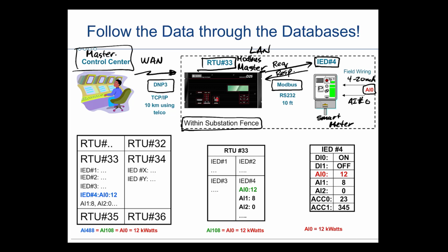It says it's being communicated over RS-232. So therefore we could say that that's a point-to-point connection. Notice how it's under 50 feet, 10 foot length. Know that that would be a null modem connection, wouldn't it? Because it's terminal to terminal. Null modem, or crossover.